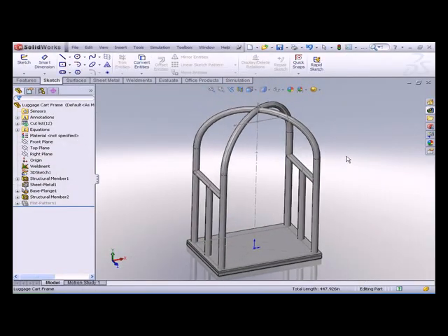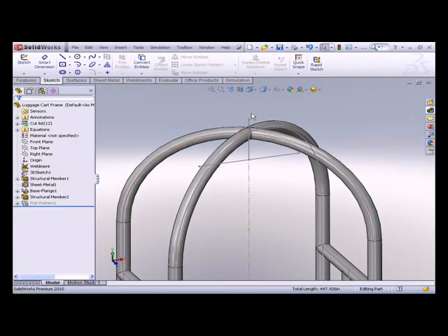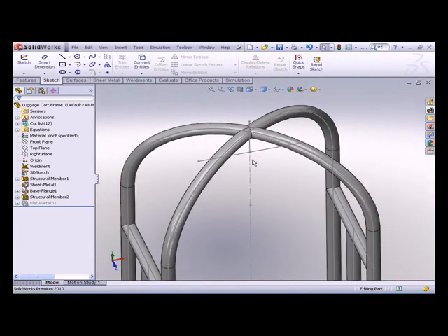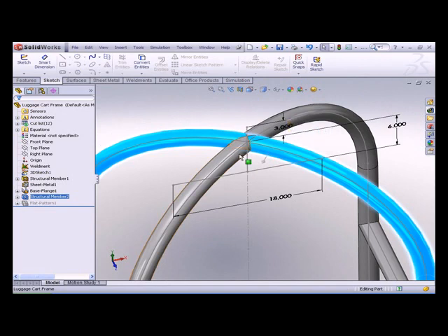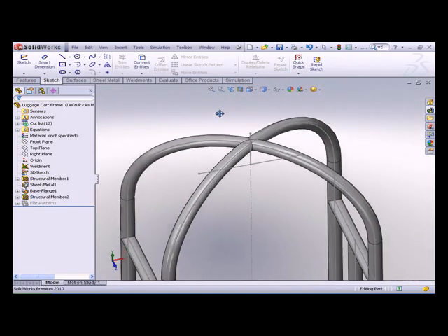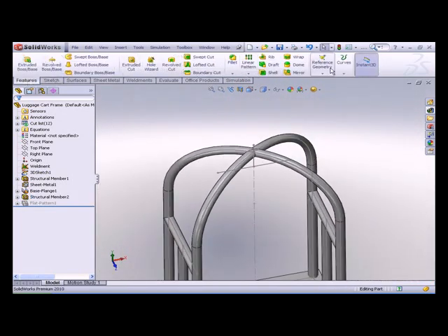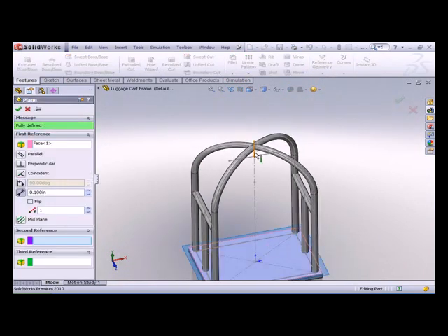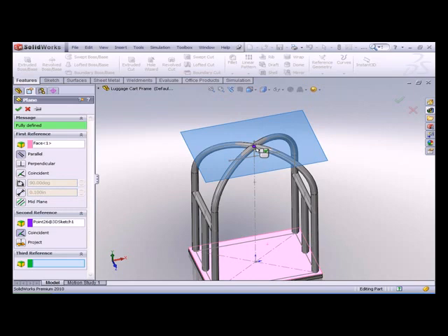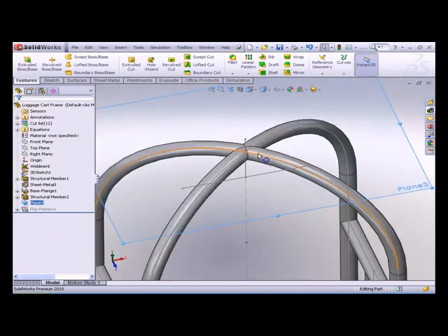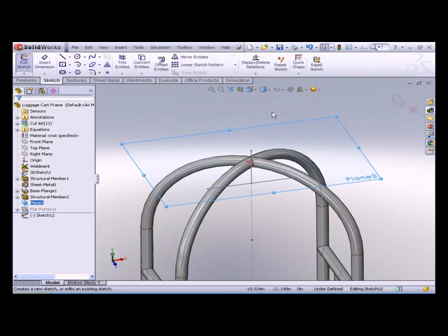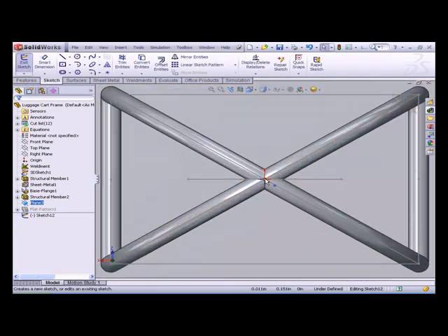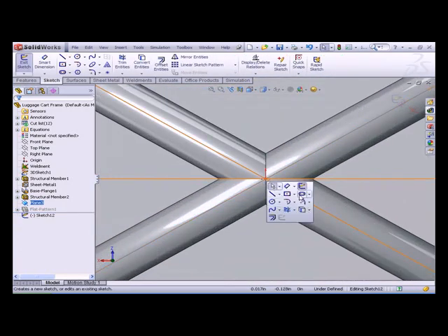Okay, so I've got a piece up here. I actually need a hexagonal member. It's actually a sheet metal block, and it's going to be where all these different members meet up. So in order to do that, I need a plane. I love the new plane functionality inside of SOLIDWORKS 2010. Simply pick a face and grab a point, and it creates a plane parallel to the plane through that point. And I can very easily come in here. Always go normal to your sketch. It helps you kind of see what's going on, understand where you're at.